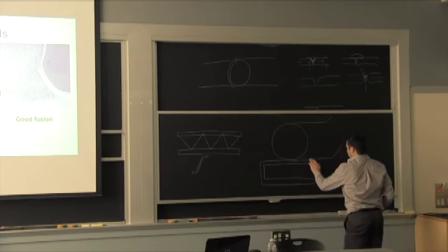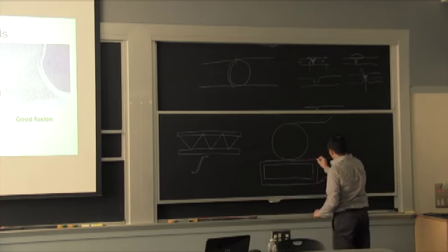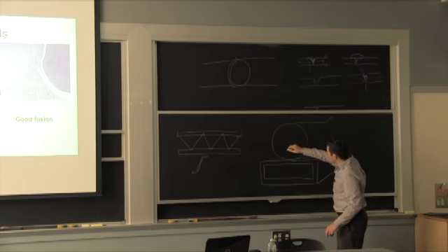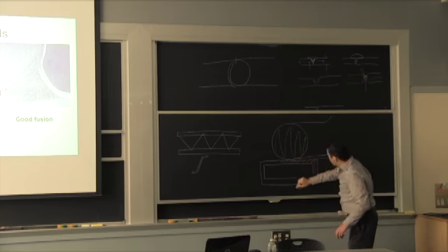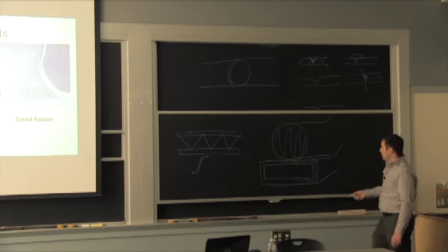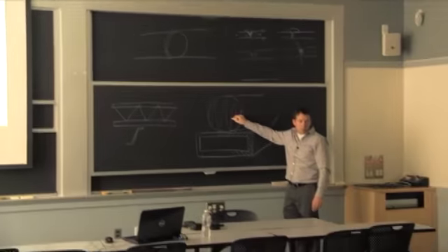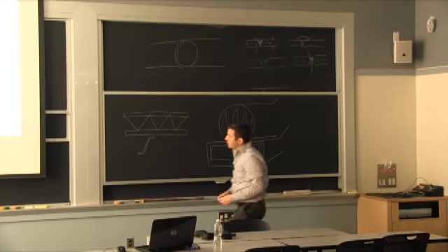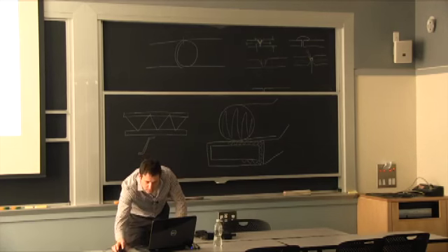So now, hopefully we can agree this is thicker, because this is a solid piece, so it's thicker than this component here. And if I want to weld them together, I'll need to put more heat in this component. And that's what they did. If you look at the image here on the cross section, there's quite a bit of melting here. There's melting on this side as well, and there's no melting here.